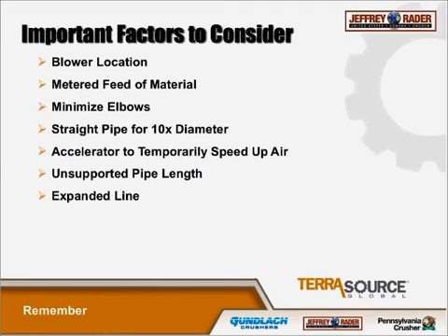Speaking of long systems, the expanded line concept is very helpful with these long systems because typically you're going to have higher blower pressure. If you remember back on the first or the second or third slide, the pressure decreases over the length of the pipe. So the longer system you have, the higher pressure there's going to be. And you'd like to decrease that pressure.